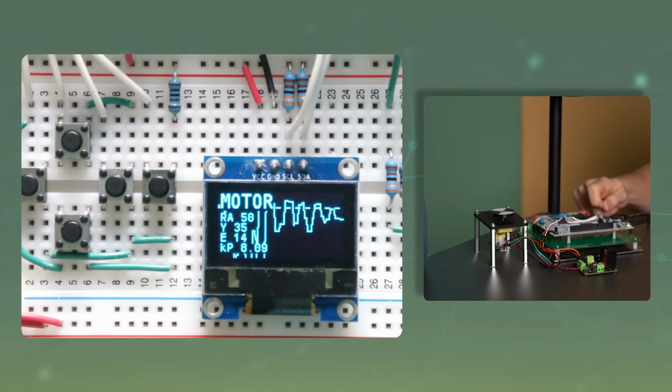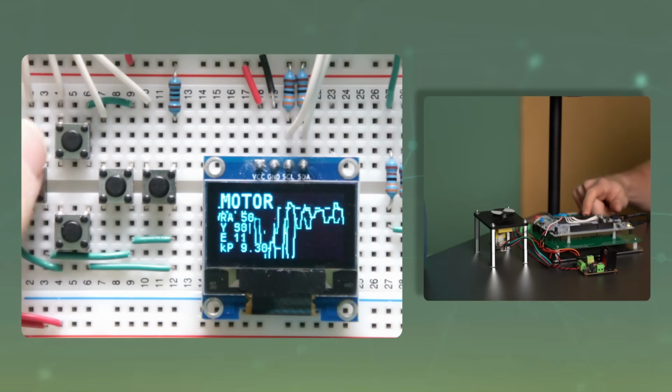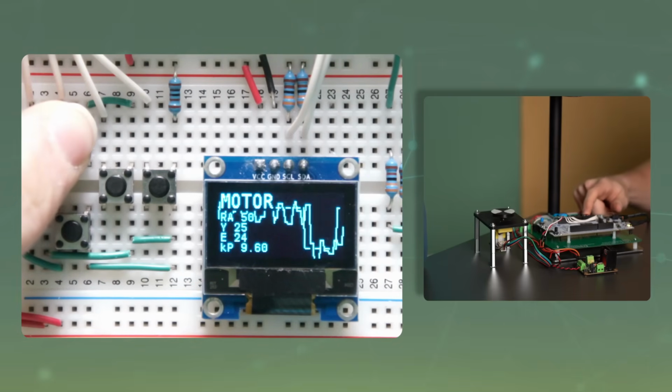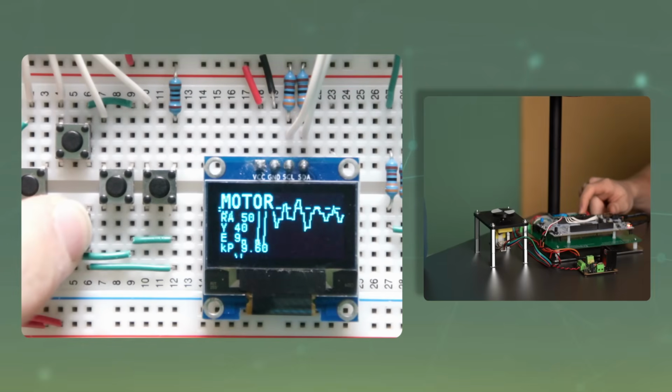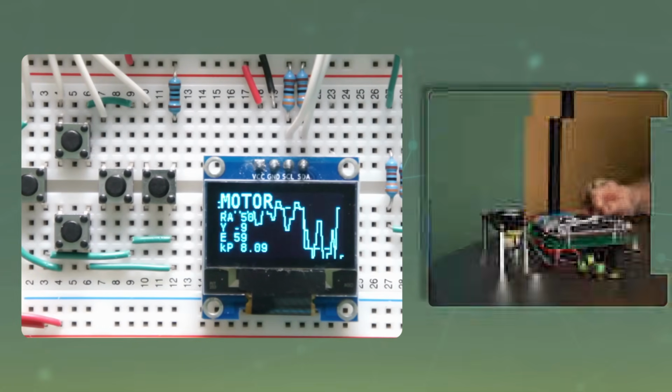If we increase the Kp further, we can see that the amplitude of the oscillation starts to rise, so we've gone beyond the state we are looking for. Let's return the Kp to the value where we experience the constant oscillation. In our case, it was about 8.1. There is no need to be extremely precise about this value, as the empirical formula we will use to calculate it will only give an approximate result anyway, not the best possible one.